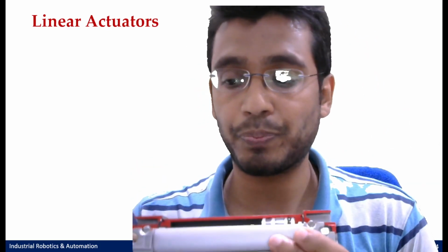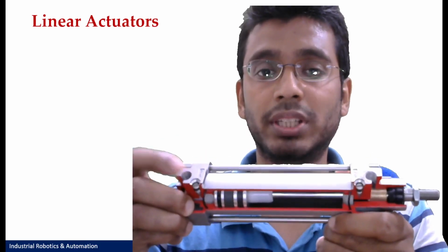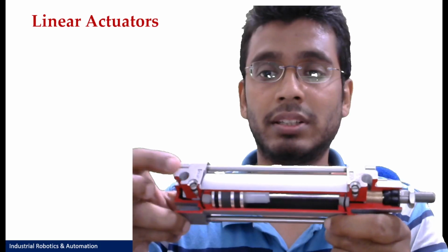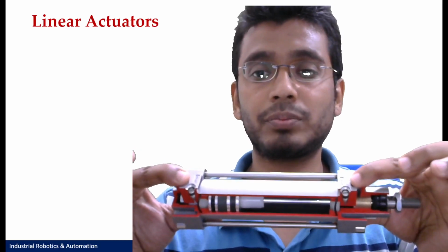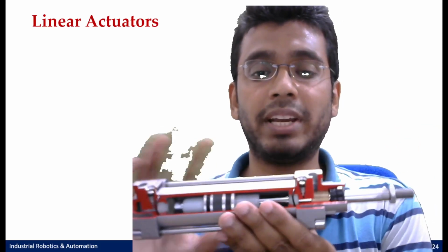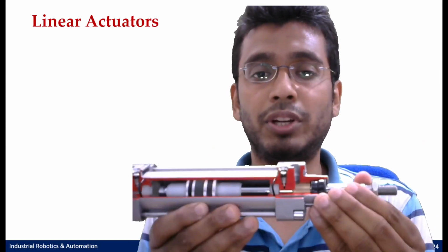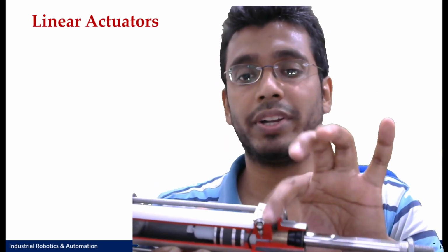Now let us see another example, your double acting cylinder. Let us see it the same way. This is a double acting cylinder. You have two ports here, again cut. One port is here, the other port is here. When you put a pressurized line here, the cylinder would extend, and since this is not a spring mechanism, it will stop in between also wherever you want, and while extending, the air would drain out from here.